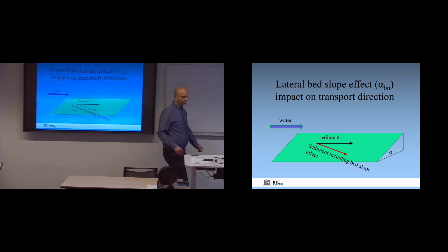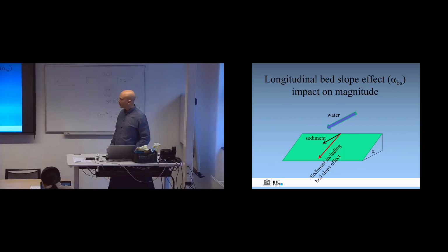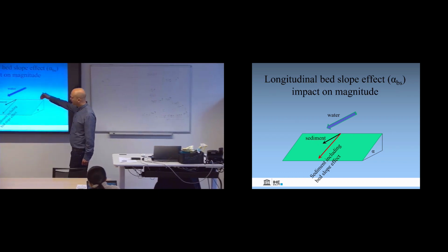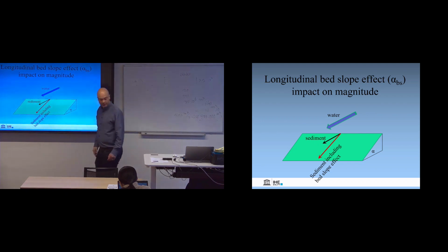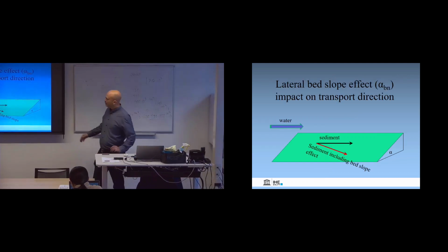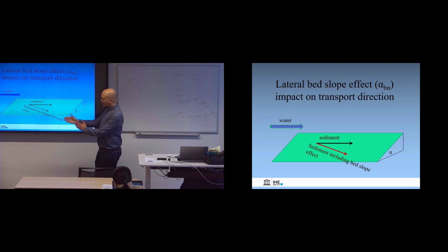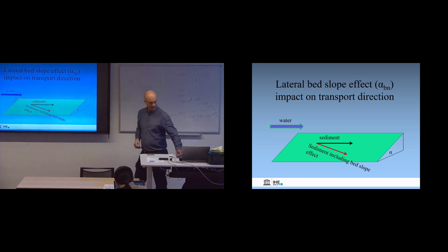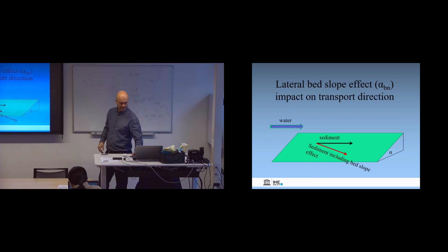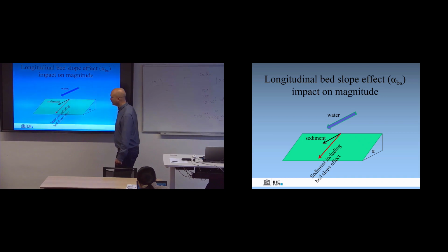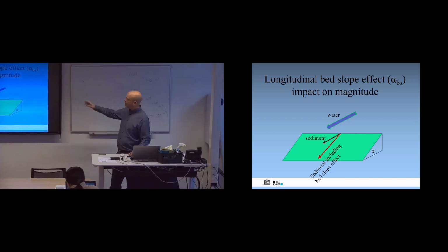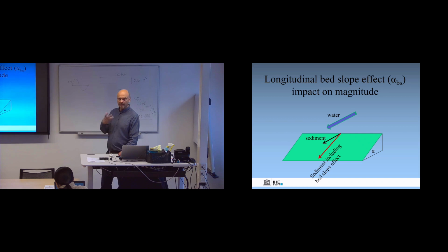That's in your morphology file. And similarly, you also have that if the inclination is in the direction of the water flow. So this used to be when the inclination is perpendicular to the water velocity direction, and this is when it's aligned with the water flow. And this is called alpha Bs. Well, these are important calibration parameters in your run.